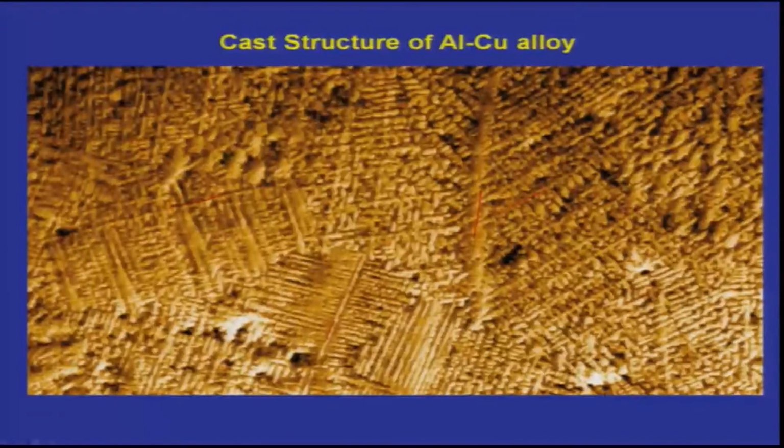In pure metals the reaction will normally be uniform, but in alloys the reaction will be preferential. Some elements will react more strongly than others, and because of that the structure is nicely revealed under optical or SEM microscopy. In a pure metal dendrites are also seen, but they are known as thermal dendrites, as I told you.